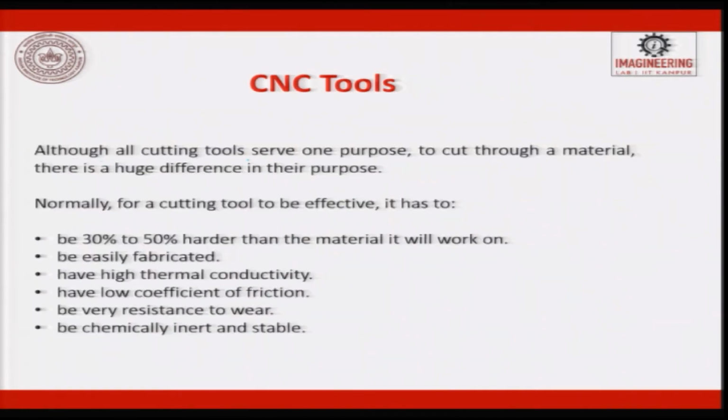Although all the cutting tools serve one purpose, to cut through a material, there is a huge difference in those purposes. In some places, there is a lot of variation in the workpiece material, so the tool has to have enough toughness. If it is a complex job machining, the tool should give us the flexibility of regrinding.